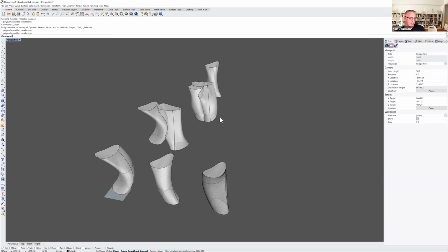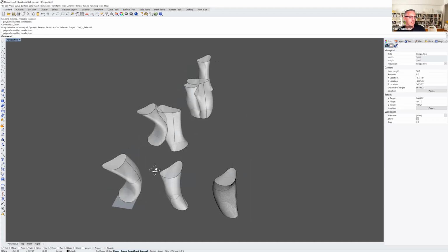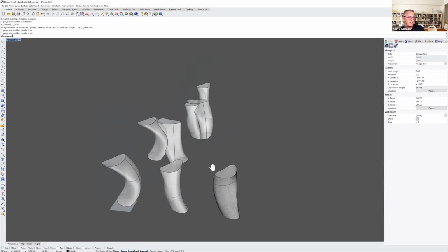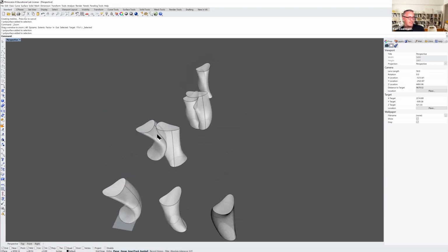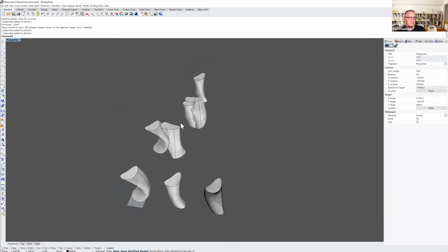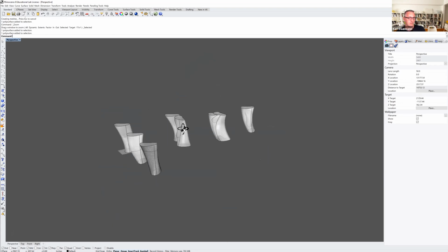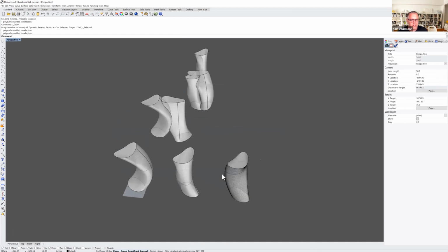And so the other thing that I'm trying to start to show with this is the way that you can kind of quickly make some iterations, right? So we used the same 3 shapes, and then we kind of copied them and we made a different set of relationships between the 3 shapes, which gave us different lofts. And then we can even just start copying these, intersecting them or unioning them, differencing them, doing any number of things as a way to produce.